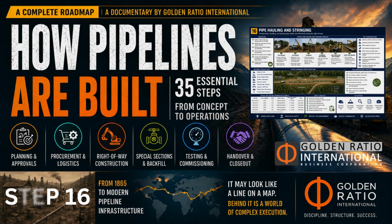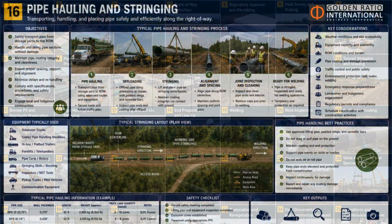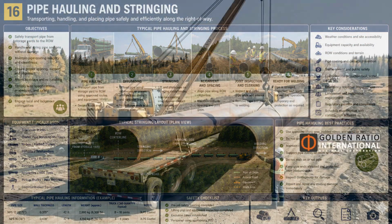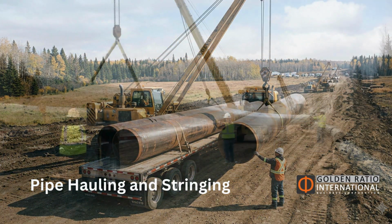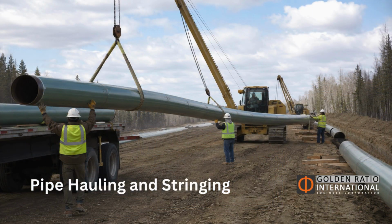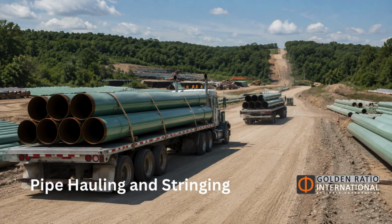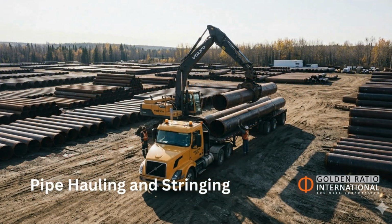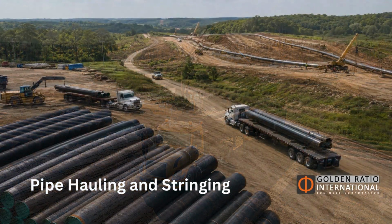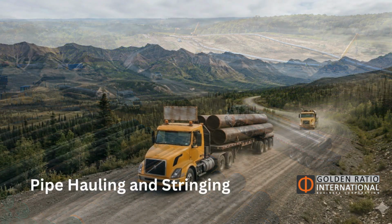Pipe hauling and stringing. Once the right-of-way is prepared, pipe must be moved from the material area to the working area. This activity includes unloading, handling, hauling, and stringing pipe along the route. Pipe joints are placed beside the trench line in the correct sequence, so bending, line-up, welding, and installation can proceed efficiently. The work requires careful handling to avoid damaging coating, pipe ends, or identification markings.